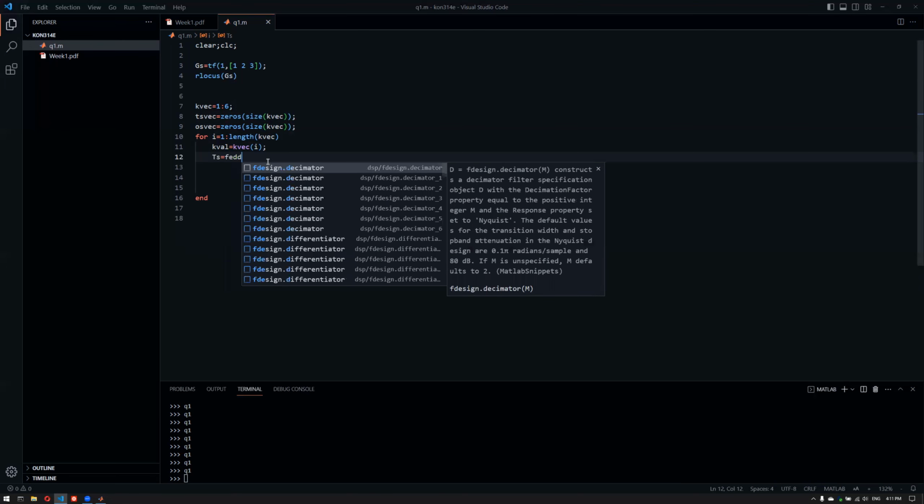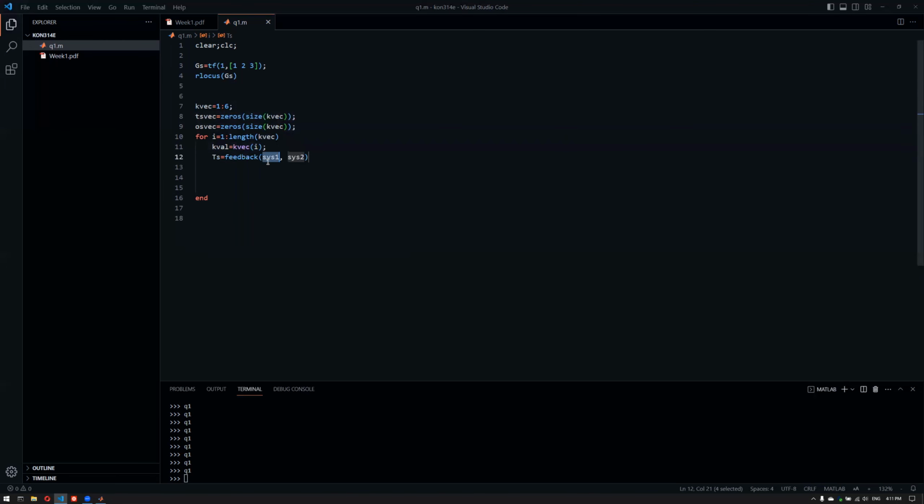I can just use the feedback command here, where I provide kval times gs, comma 1. If you don't want to use this, you can also use kval times gs divided by 1 plus kval times gs. So I'm just going to show you.